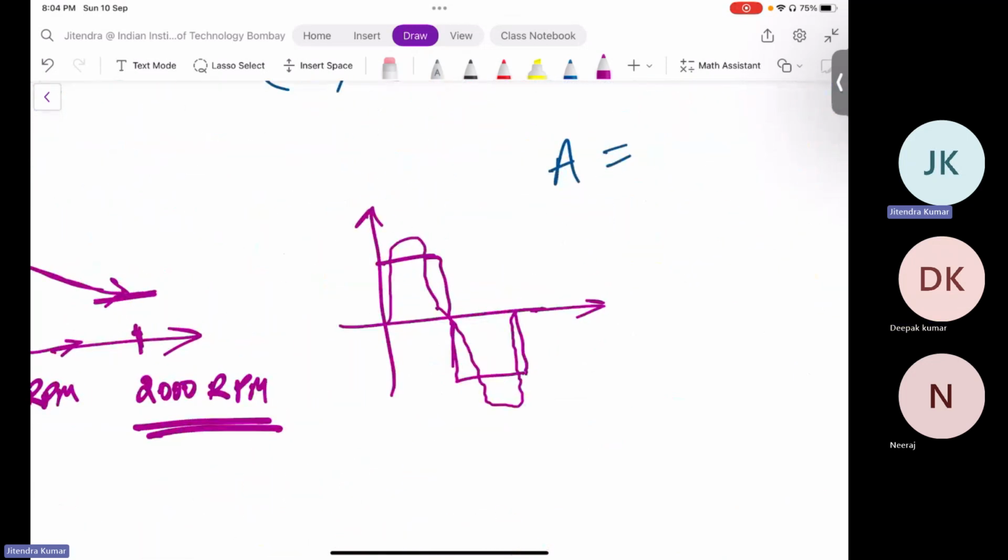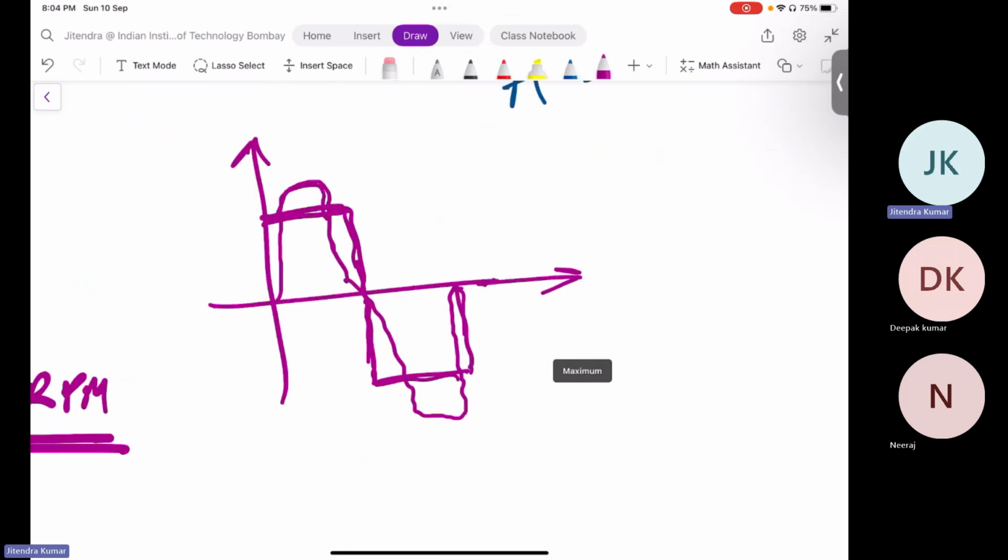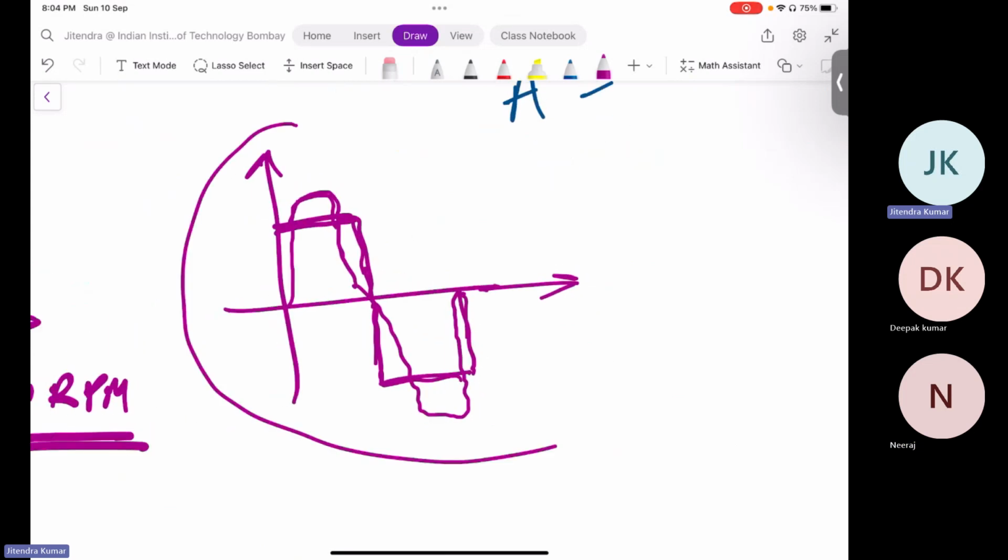Yes, sir. Now coming back to the earlier question, what was your question? Okay, so we are achieving BLDC operation here. We are giving a square wave of current, wherever this kind of EMF is there. Now, what is the problem with the square wave current? See, you understand this graph: there is a square wave current, and this kind of EMF, which I have shown you earlier, is induced from the coils.